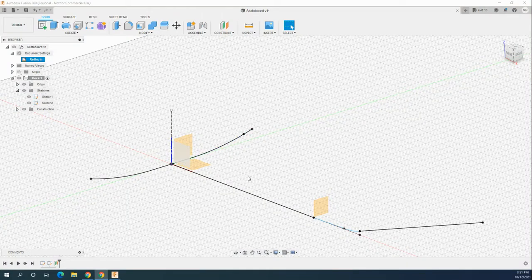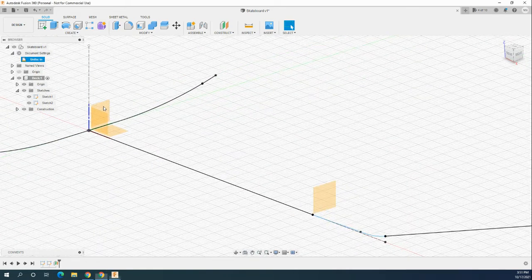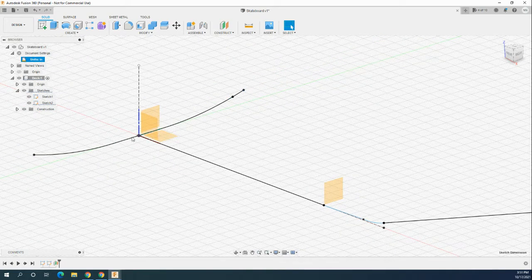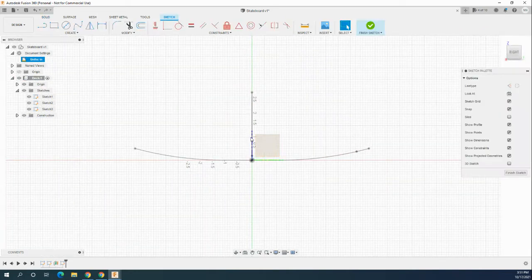All right, in the last video, we just finished up creating this extra plane that is parallel to this plane back here in order to get the same skateboard shape, the cross-section shape, drawn onto here. So what we're going to do is right-click on this, and create, no, I don't have the create sketch, so I want to click out in the white space and try it again. Right-click on the plane, create sketch. I must have had something else selected when I did that.